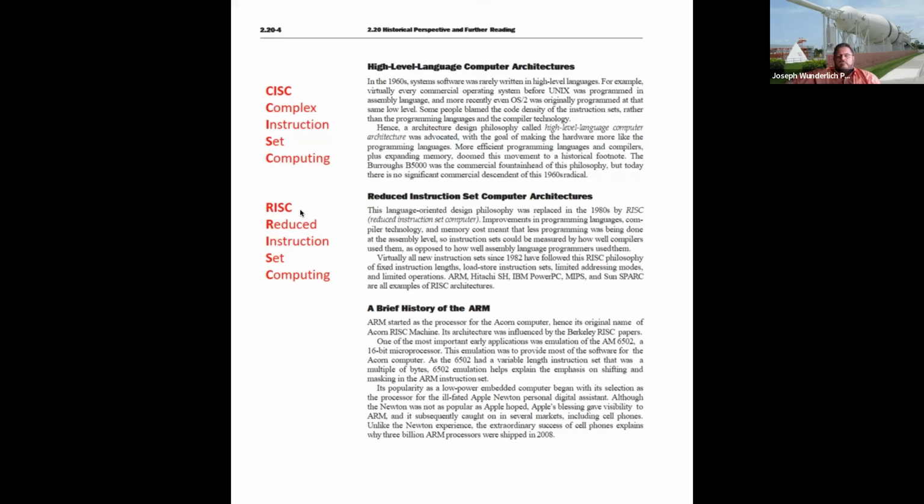The control unit that controls the data flow, or the finite state machine we discussed in the 332 class, digital design 1, is hardwired instead of microprogrammed in the RISC. Also, you have more registers in the RISC instruction set, and you make use of them with a simpler instruction. So RISC comes along with a number of things other than just reducing the number of instructions.